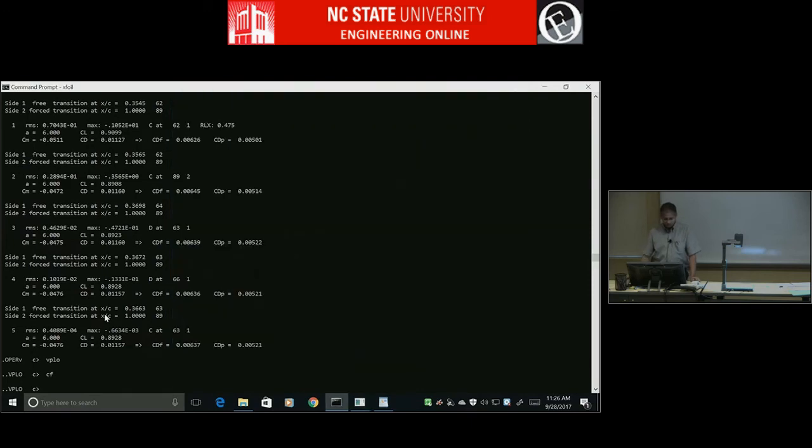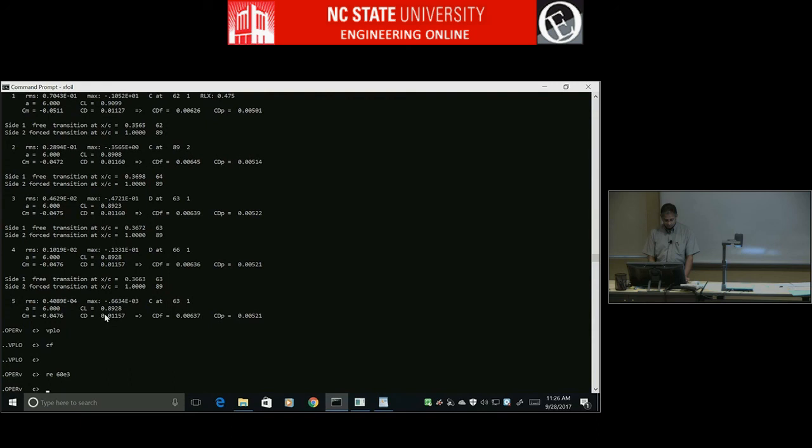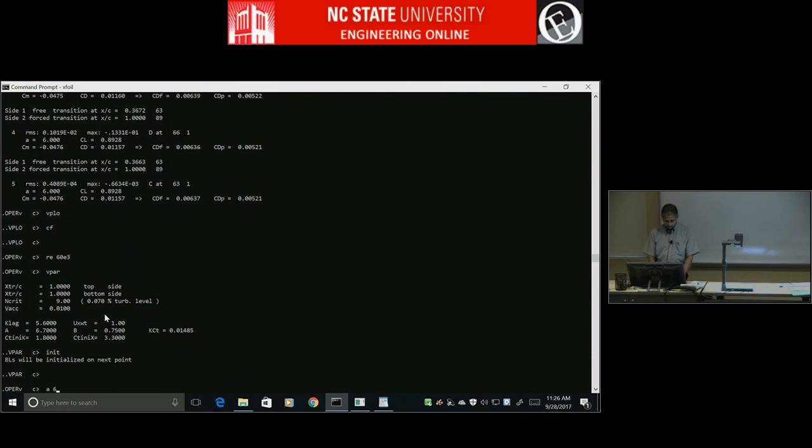Now let's reduce the Reynolds number even more. RE, what did I give? 0.3 E6, right? Let's go to 60K. 60 E3, 60,000. Oh, I should do VPAR init, alpha 6.